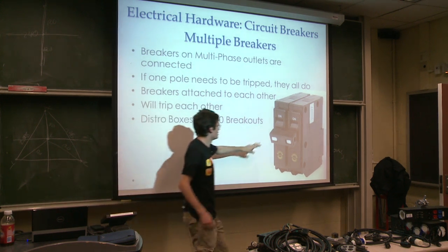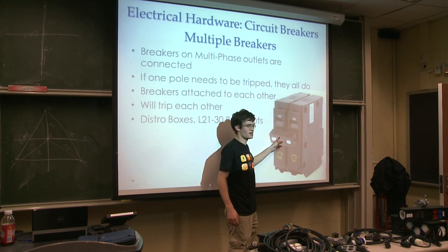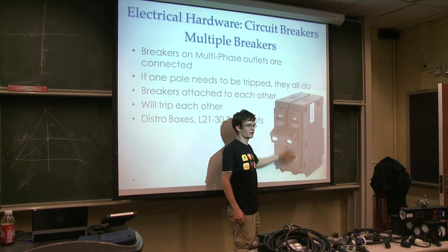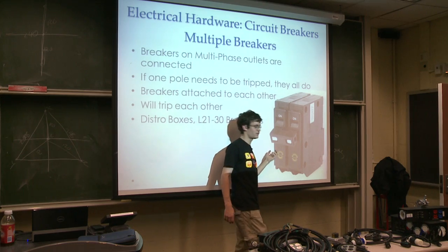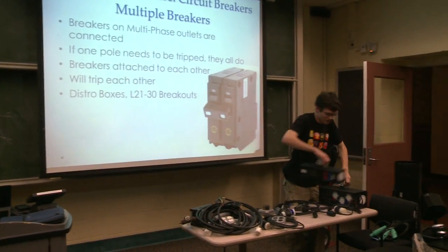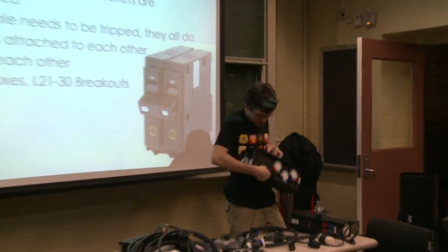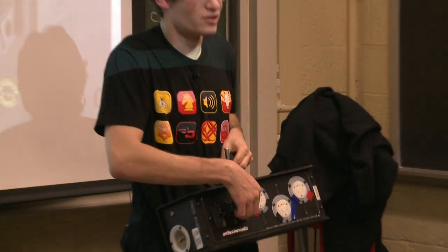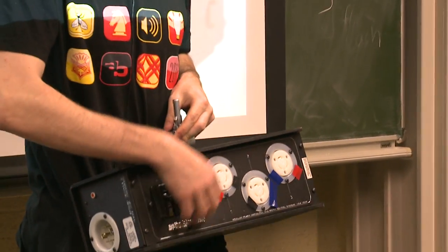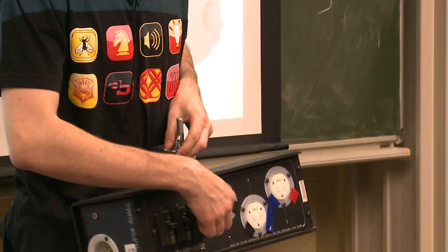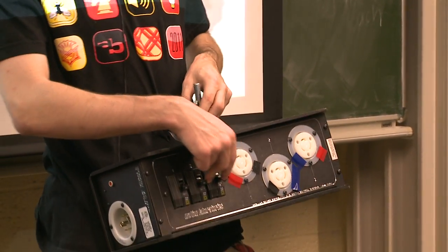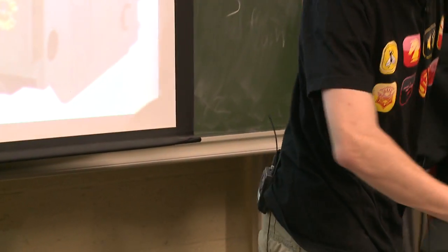You either get 2 single breakers which have some kind of plastic thing over them, and when they turn off, they are forceful enough to turn each other off, or you'll get this, which has breakers connected internally between the 2 of them, and even though it's just one little switch, it's actually connecting 2 hots and turning them on and off.